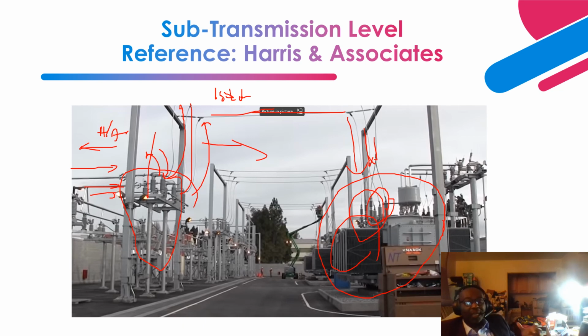Insulation coordination is achieved utilizing insulation coordination studies, so that is how the number of surge arresters is determined. In addition, the insulation system of this transformer is designed to withstand lightning and switching surges.